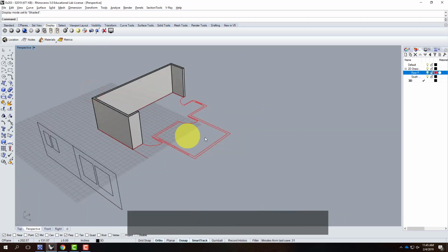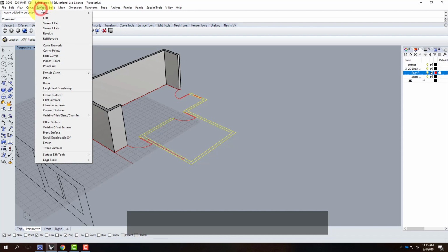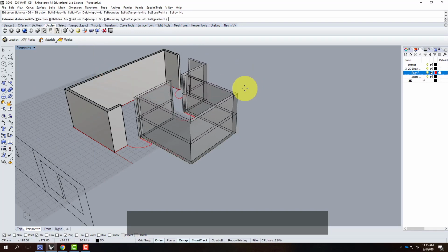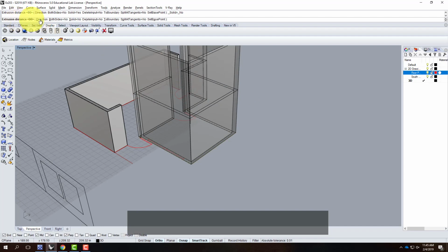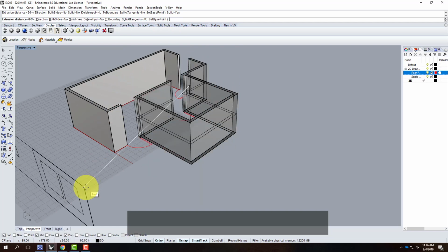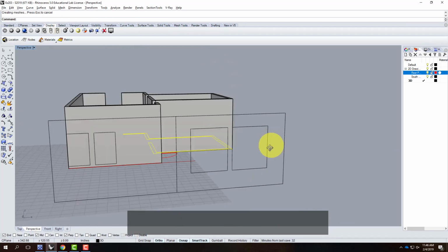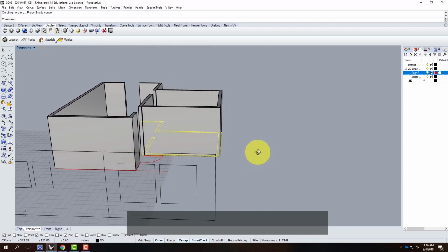And I'm going to do the extrusion of this half of my building. So once again, I'll go up to my surface menu. I'll choose Extrude Curve Straight, or type in ExtrudeCrv. There's my extrusion starting to happen. I've got my distance already set. Both sides, no. Solid. Oh, yes, we do want solid. Delete input, no. OK, I'm good. And this time I can actually just snap to here, or I could snap to here, and I get to the same end result. So go ahead and click on that. And I now have the beginnings of my building where I've done my extrusion.